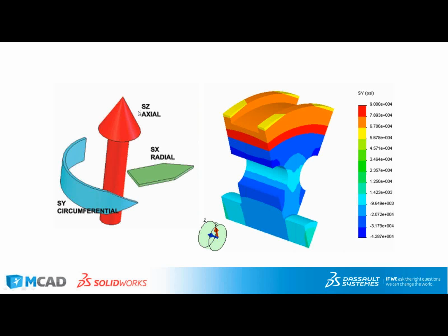Another thing to highlight, if you're not aware of it: when we're looking at component values for displacement or stress, notice that those values can be mapped over into a cylindrical coordinate system if you pick an axis in the property manager for setting up the stress plot. I'll show that here directly in the interface, but this is the mapping that you get. X maps to radial, Y maps to circumferential, and Z maps to axial.